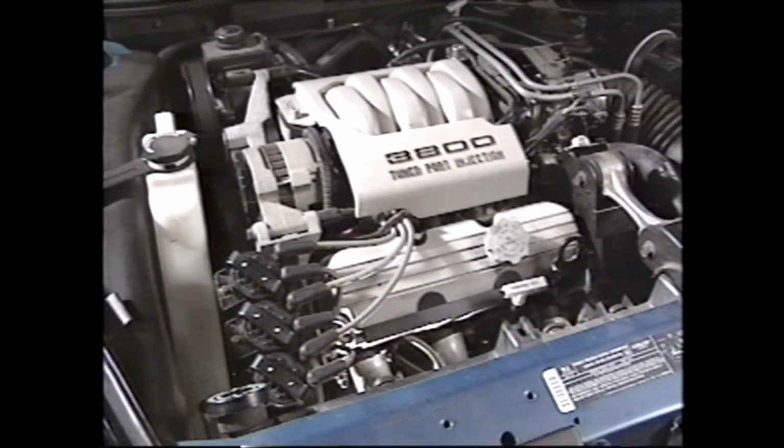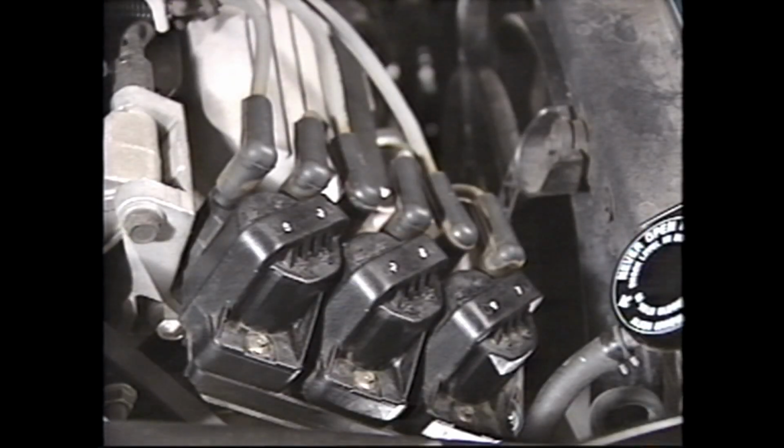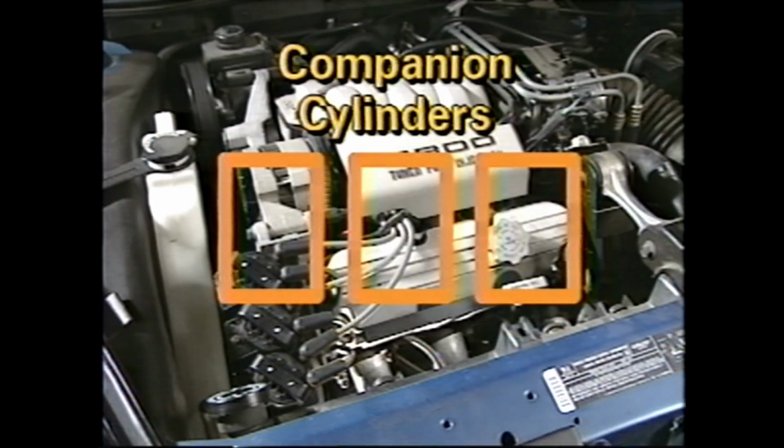Now, let's take a look at the distributorless ignition system. The principles of distributorless ignition are essentially the same as those for electronic ignition. Distributorless ignition is physically different in two ways. There's no mechanical distributor, and most of the time, one ignition coil serves the two spark plugs of companion cylinders. You can determine which cylinders are companions by listing the first half of the firing order over the second half.